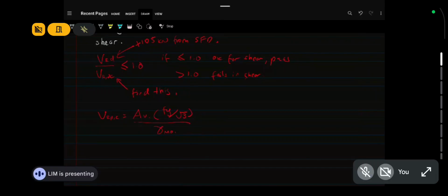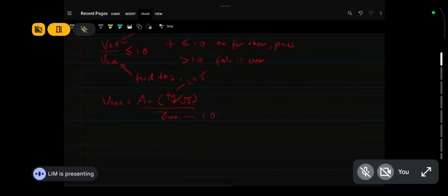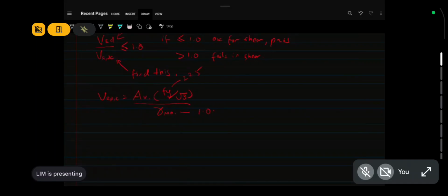All right, but it's basically this formula. Okay, VRDC is this formula. So fy is 275, square root 3, gamma m0 is always 1. The only thing you have to look for is Av. So look for Av. Now the formula for Av is...